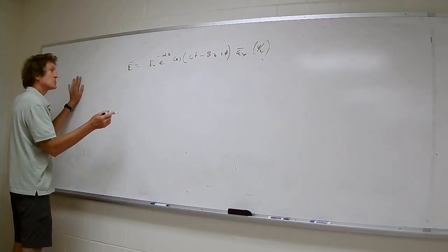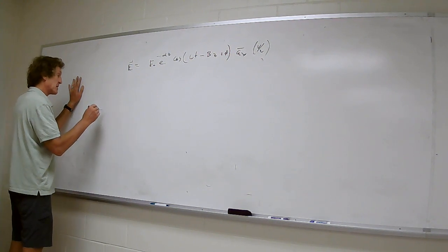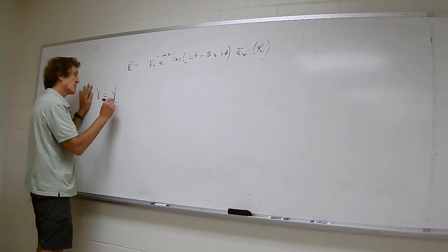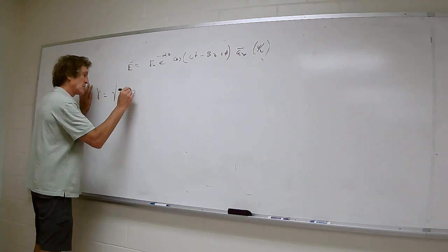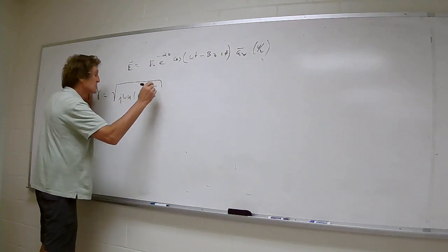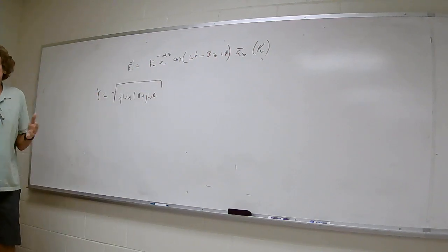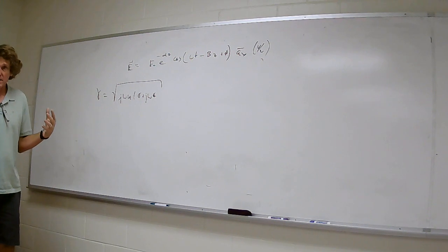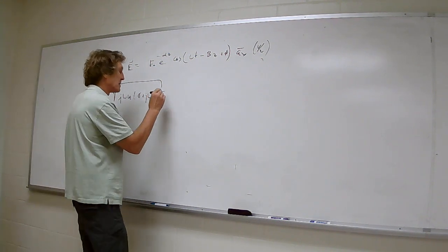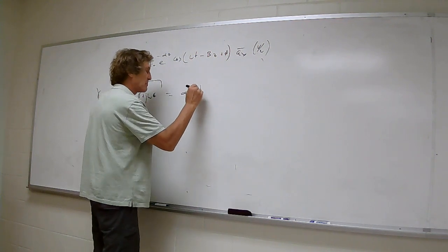So in general, if you have this type of thing, there's a propagation constant. The propagation constant is the square root of j omega mu times sigma plus j omega epsilon. Now that's assuming that it's at a constant frequency. This doesn't have a meaning if it's not. Y'all with me, class? Yes. All right. So this is equal to alpha plus j beta, right?